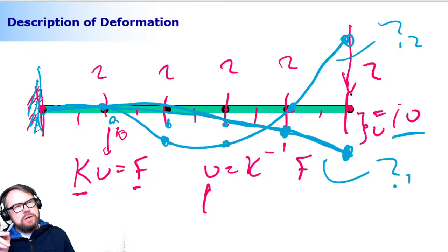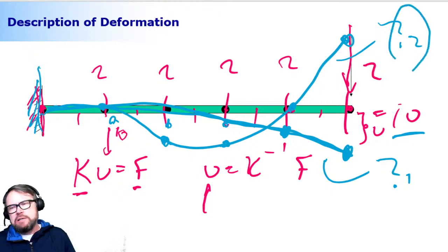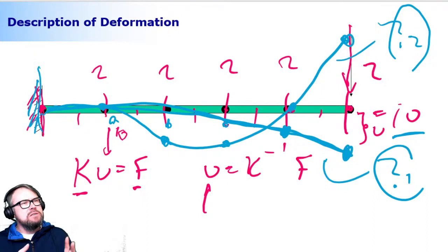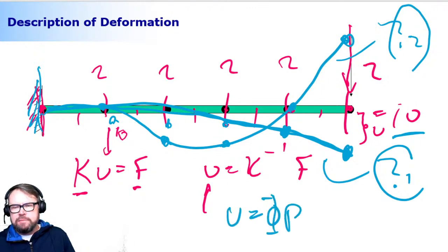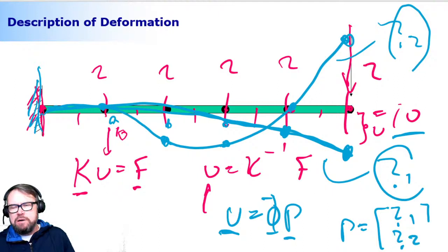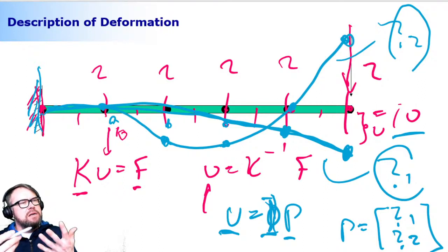But the big trick here is that instead of using 10 deformation modes and corresponding question marks, I could use just some of them. Let's say that I'm going to use 2 of them. And when I'm using 2 of them, I can build this relation. This is my nodal degrees of freedom. This is my modes, my unknowns, which this time would be unknown number 1, unknown number 2. This one here is a numerical representation of the ways nodes can move with respect to each other.